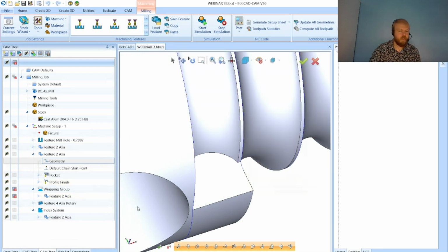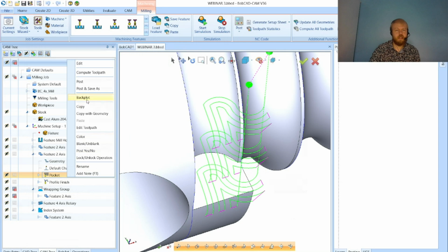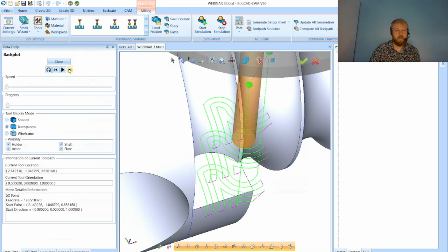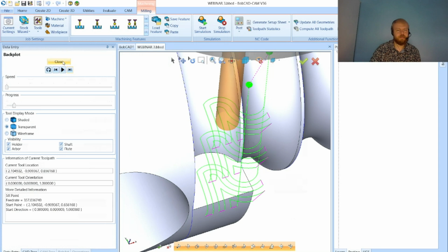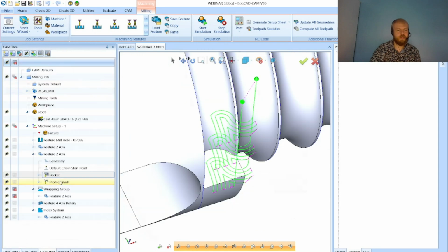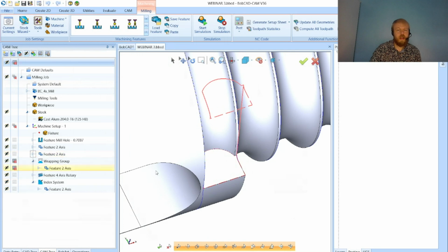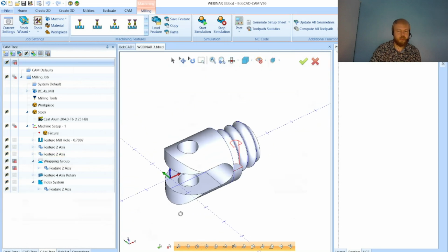There you go. So selecting that surface, it will detect the open edges of the surface automatically, start from the outside and work its way in. And I'm doing a depth of cut here for 3 passes, or 3 depths there, and then a profile finish around there. Then we get into the 4-axis machining.